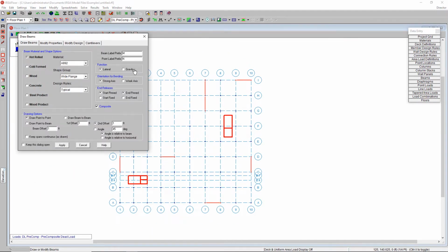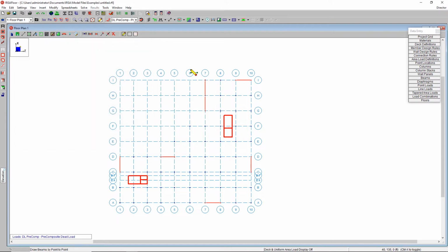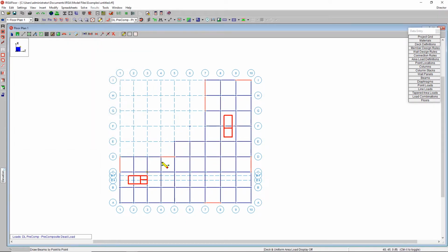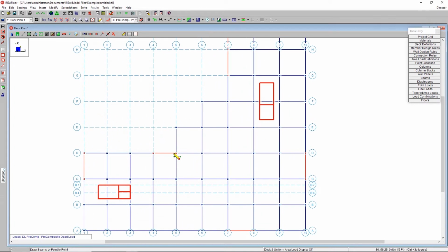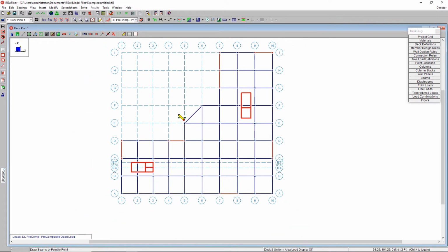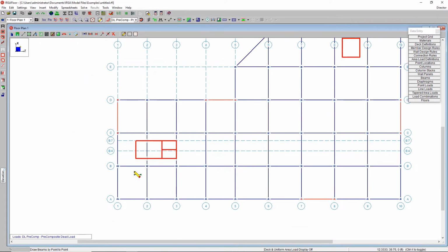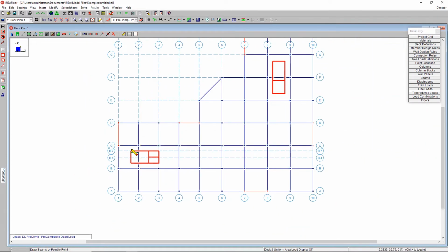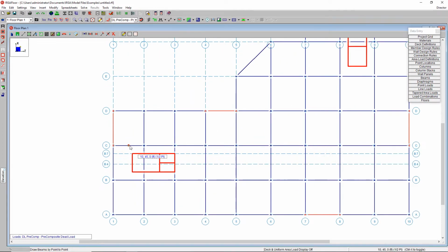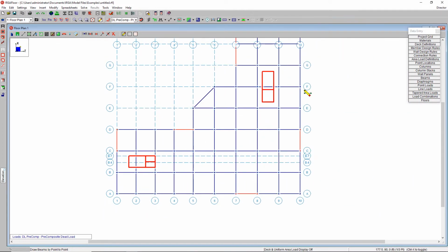For the beam system, again, we just define this as gravity, and we'll draw this around the structure point to point, and I can just continue to rubber band most of the structure. I can really do a lot of rubber banding. It's very easy to do that, and then connect some bays that are not connected like that. But then you'll find that there are areas that you want to connect, but it's not as easy. There may not be a snap point for you. It's easy to do those things here.